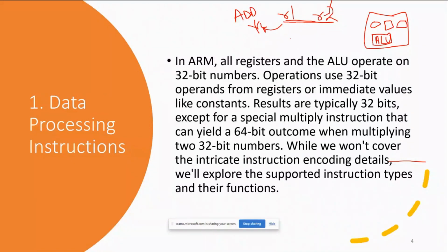This is one type of operation, or the operand can be an immediate value, a constant. Like we can add R1 with 2. R1 means the value stored in R1. R1 is a register, and the value stored is suppose 5. So 5 is added with 2. Here 2 is not any register, 2 is a constant value. These types of operations can be done either with the values stored in registers or a constant. But we are not adding with values stored in any memory location. First, we have to bring the data from the memory to a register.